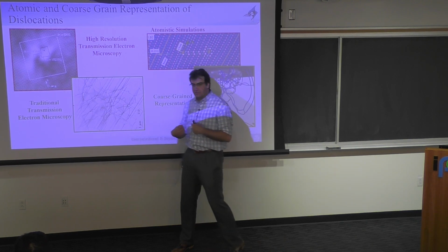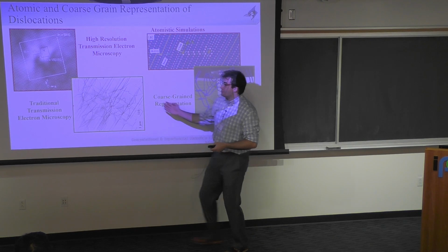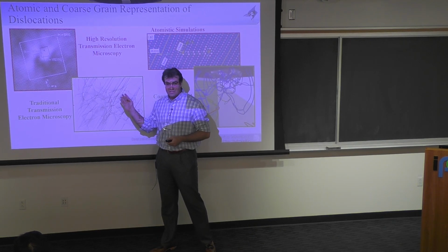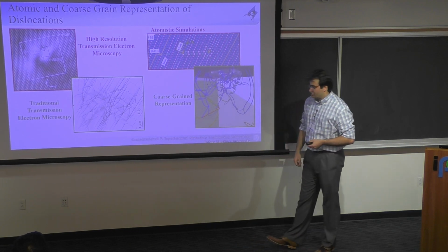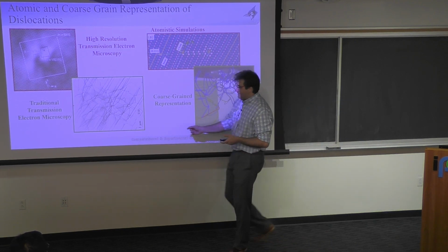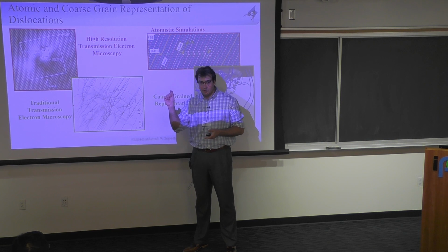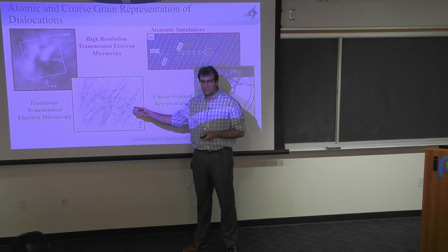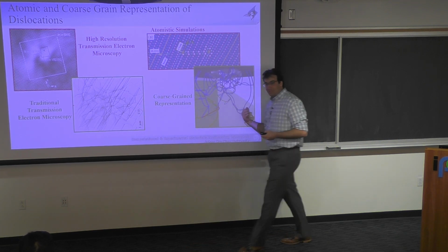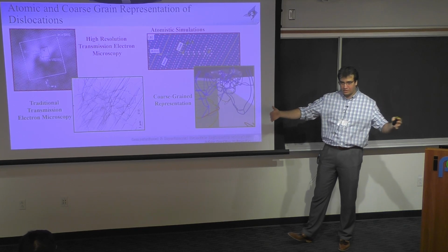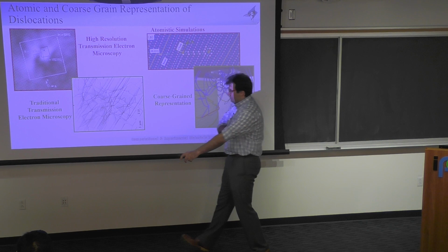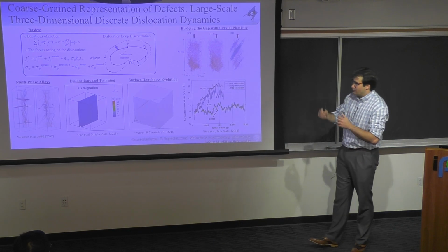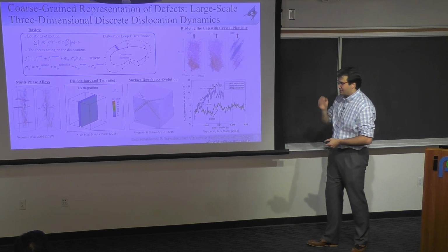So what we're trying to do in the discrete dislocation dynamics world is look at the evolution of dislocations at the level of traditional TEM. The major difference is TEM requires very thin foils to be able to observe these dislocations. In the discrete dislocation dynamics world, I can actually go to microns, and tens of microns, that the TEM experiments are not able to access. So that's my one slide introduction of what discrete dislocation dynamics is.